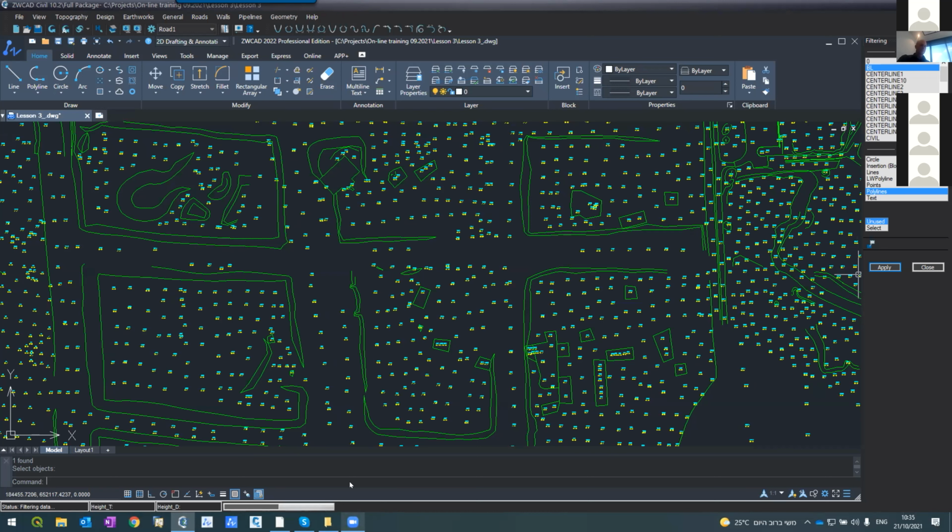Where can we see the filter icon? When you go to the topography, filtering can be done to many things. We can filter break lines, we can filter points. Like Mr. Anis here asked me, if I have a DWG of points, how can I do it? So there's a filtering for points, and filtering for break lines. How do we see the filtering for break lines? We go to topography lines from the menu.